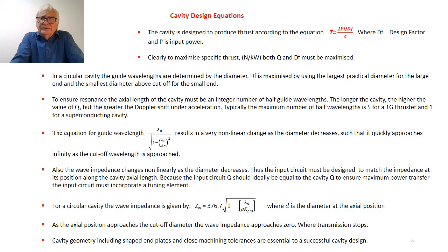So again, cutoff, very important in the consideration of where you put the input circuit and indeed how you design the input circuit. The other important point to note about cavity design is that the end plates have to be shaped, and there needs to be close machining tolerances applied to ensure a successful cavity design.